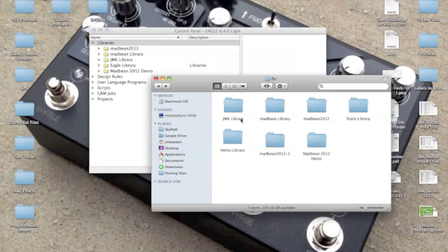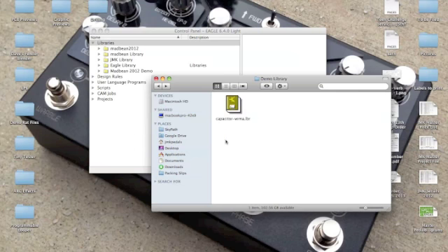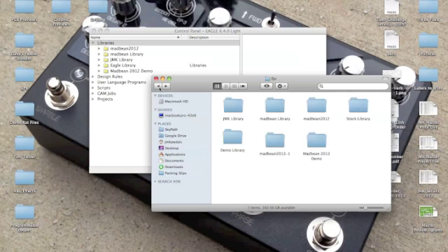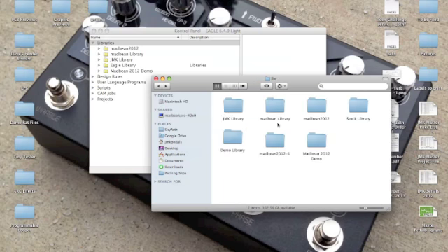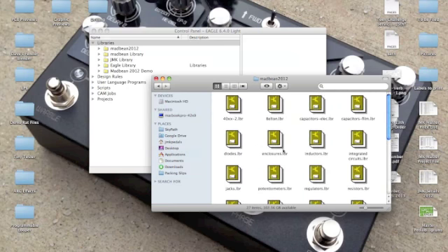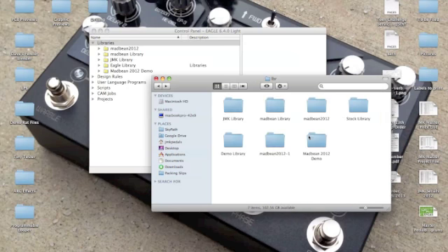The hazard with that is that sometimes you may edit a library part in here, and then when you go to use it in a different library, it does not have the same pad spacing. So you have to be very sure that what you're using is what you're always going to be using, and be ready to make edits to a part in another library if for some reason you're using that.